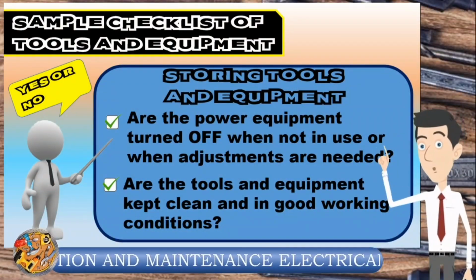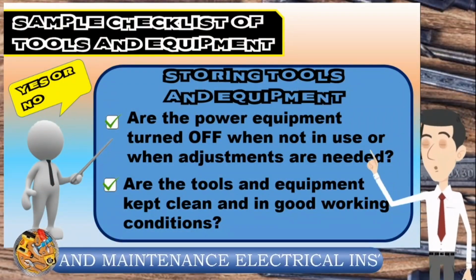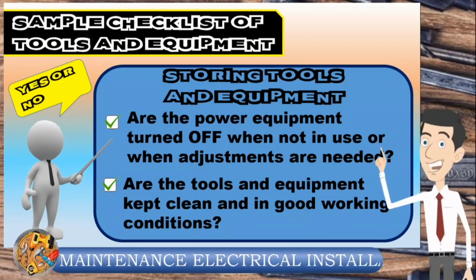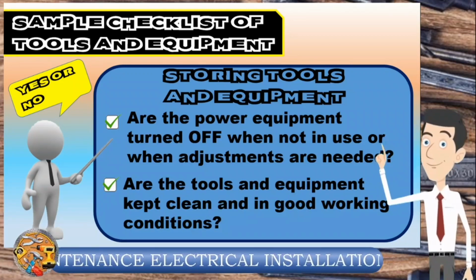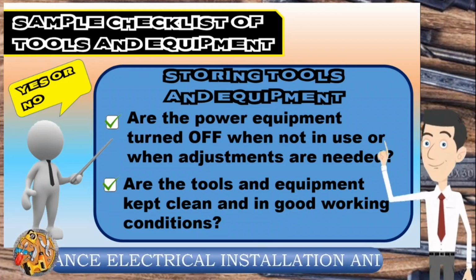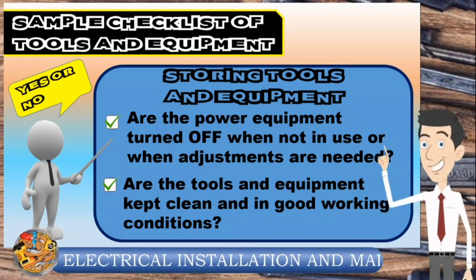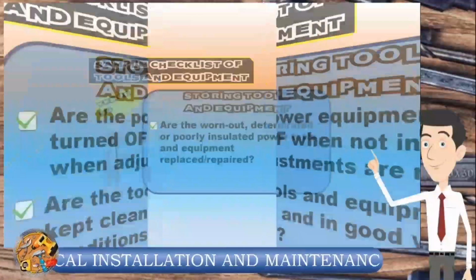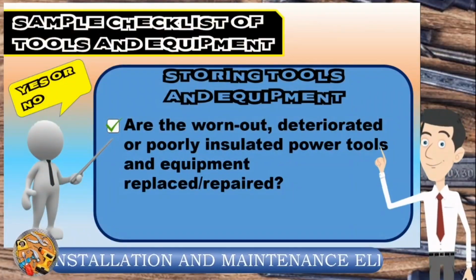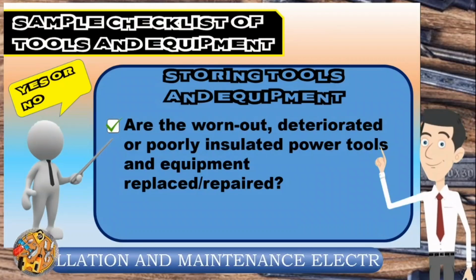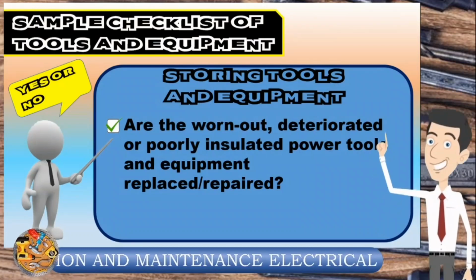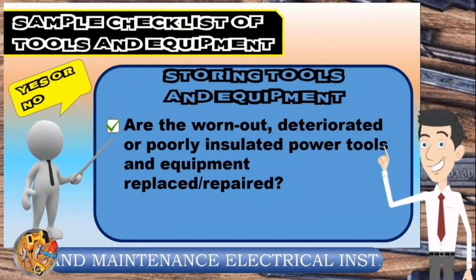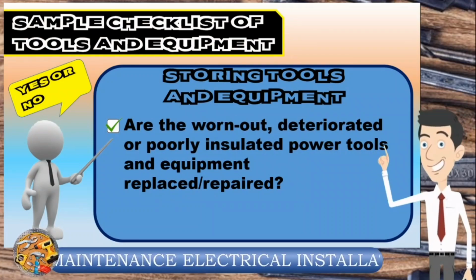Are the power equipment turned off when not in use or when adjustments are needed? Are the tools and equipment kept clean and in good working condition? Are the worn out, deteriorated, or poorly insulated power tools and equipment replaced or repaired?